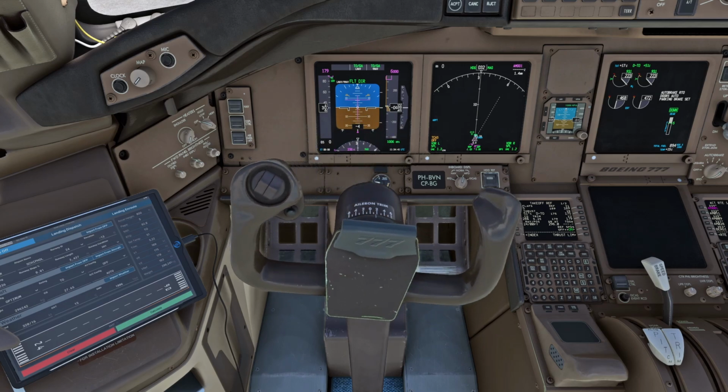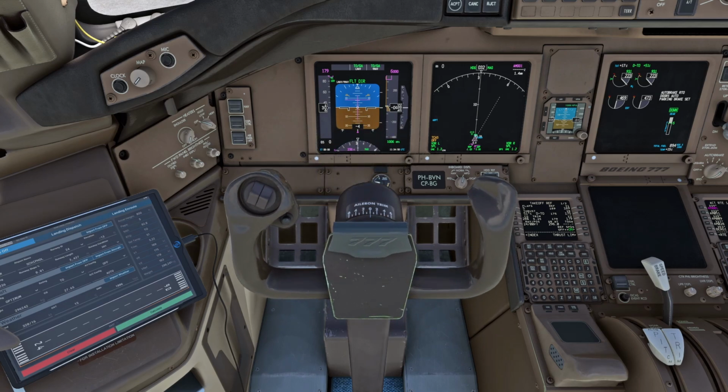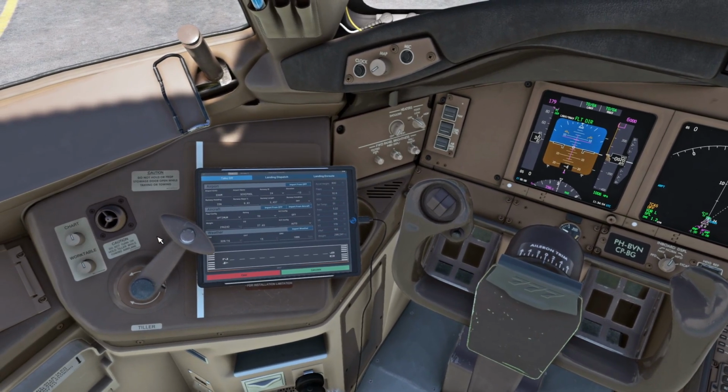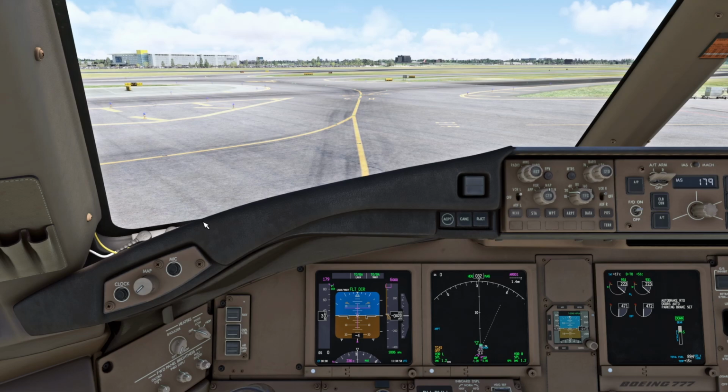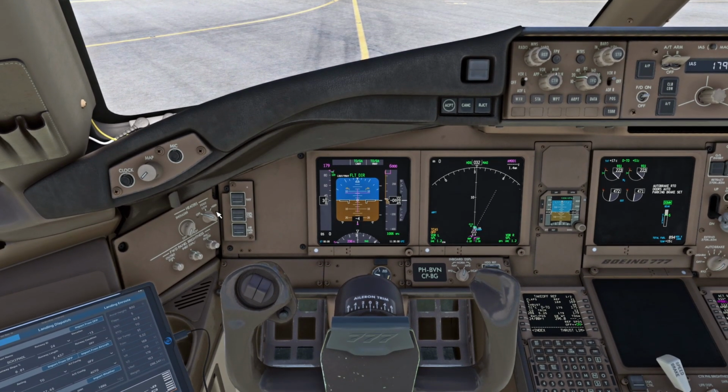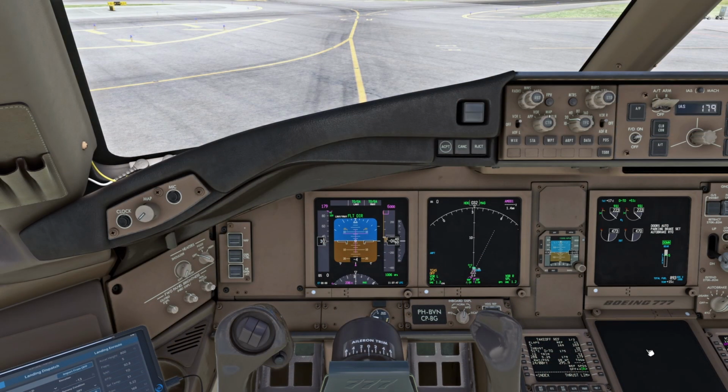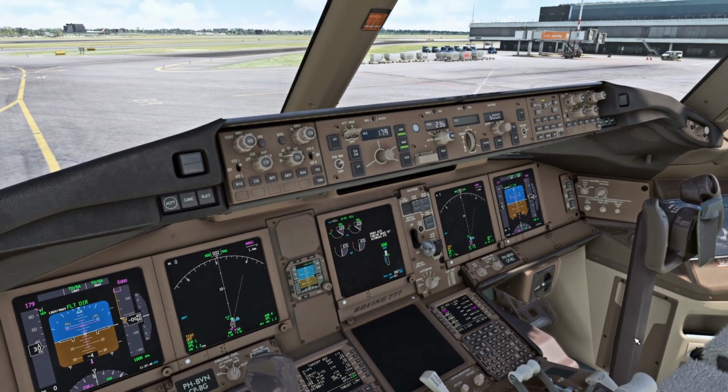Next we check the rudder. You would in real life also make sure that you hold the tiller in that case to prevent nose gear movements. So we're going to move them in both directions. Again, same thing, freedom of movement, and make sure that they turn nicely to center. Alright, so that is done. Now we can move to the before taxi checklist.